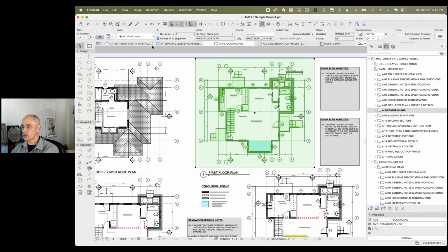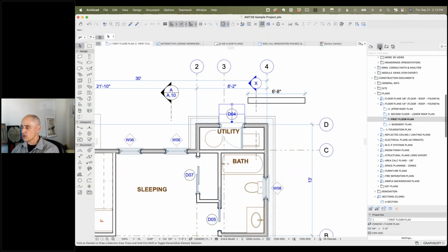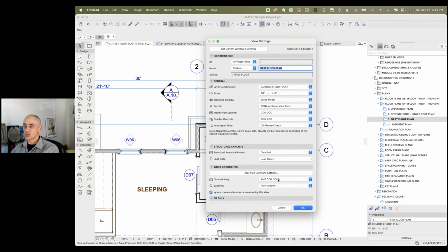When I opened the source view, it switched me over to this one. And in the view map, this is the view that's highlighted. Now, what are the settings of this view? It says use this here. So my guess is, Jerry, that you changed the settings of a dimension preference and didn't save the custom settings with a name.